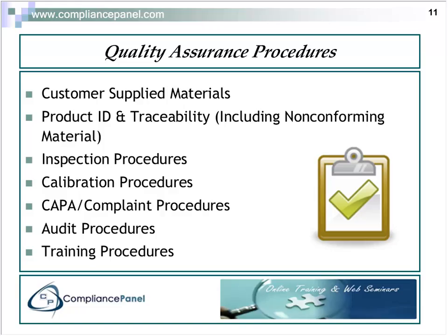So just because the manufacturer says you should calibrate this instrument on an annual or biannual basis, you may find that this instrument is good enough that there's no need to do it in that time frame.